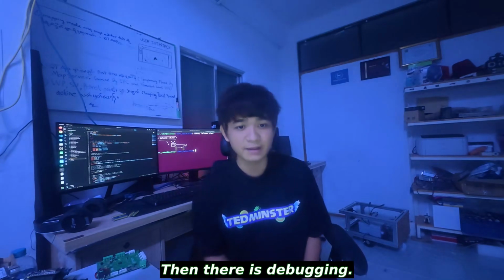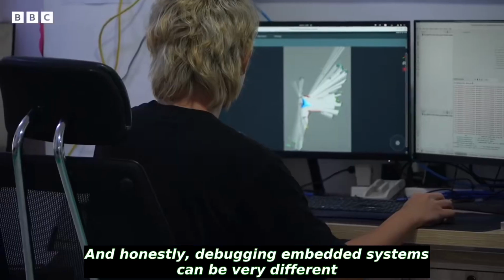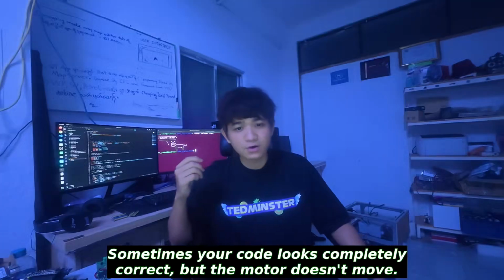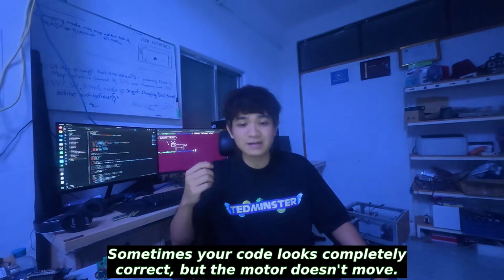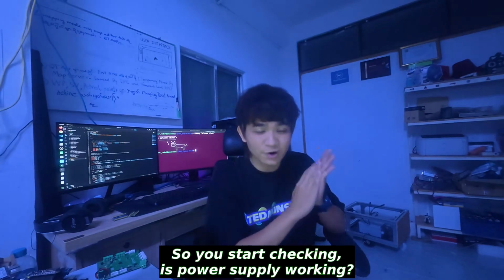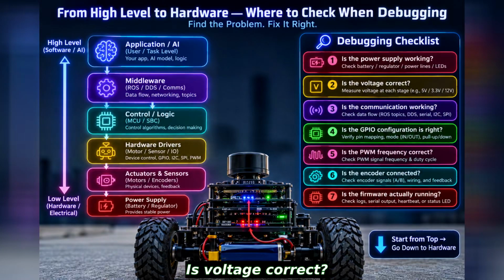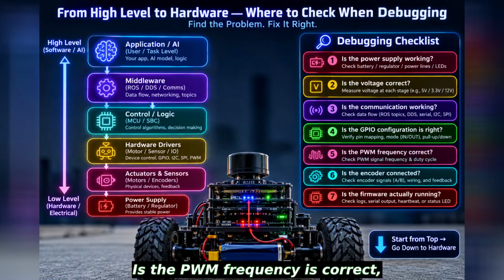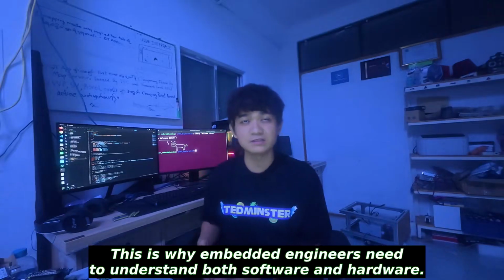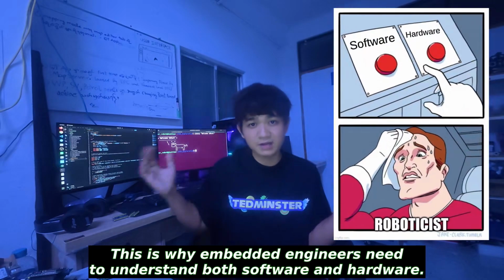Then there is debugging. And honestly, debugging embedded systems can be very different from debugging normal software. Sometimes your code looks completely correct, but the motor doesn't move. So you start checking if the power supply is working, or if the voltage is correct, if the communication is working, or if the GPIO configuration is right, if the PWM frequency is correct, if the encoder is connected, and if the firmware is actually running. This is why embedded engineers need to understand both software and hardware.